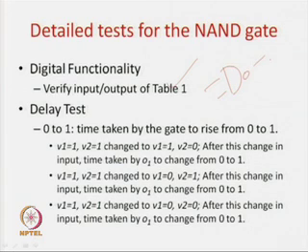Another very important part is the time, that is the delay. You might have heard, or we have already discussed in the first 2 modules, that a circuit works at x gigahertz, or the time required by an operator like an adder or a multiplier is x nanoseconds, or its frequency is so and so. All this speed depends on the delay, that is, if some input arrives here and some output arrives here, what is the time delay of this gate?